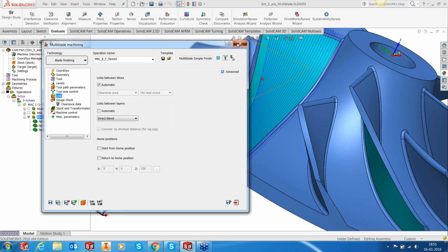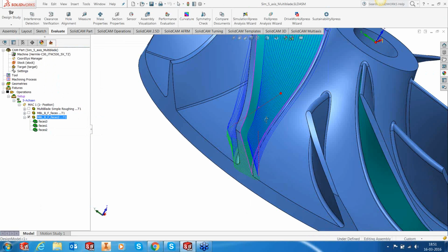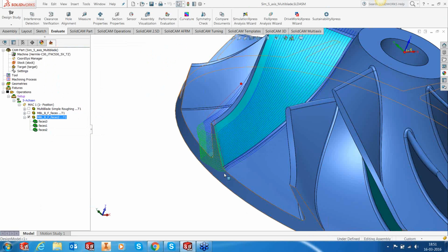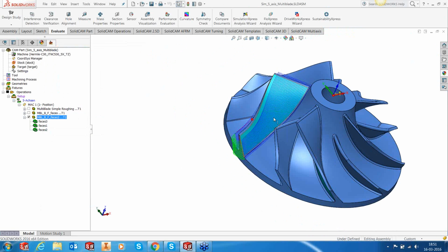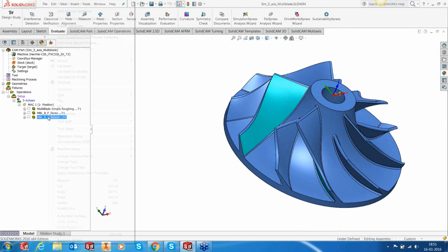Okay, calculation is done, and you can see what happens here. Instead of going to the clearance plane, I'm making a join by taking a nice blending spline out of the part, so that I don't lift every time. It doesn't look nice. You actually end up spending more time by lifting and moving to the other side. So I can join them simply by blending a spline, and this I could do because I could override its automatic parameters.